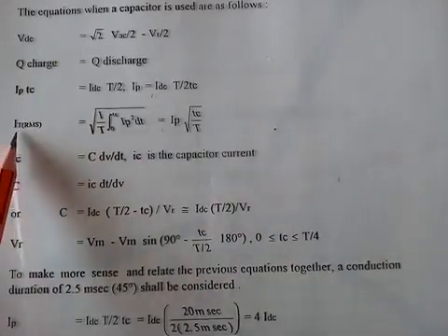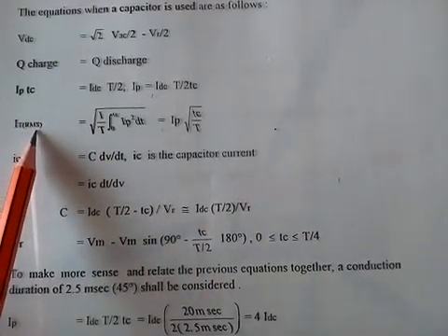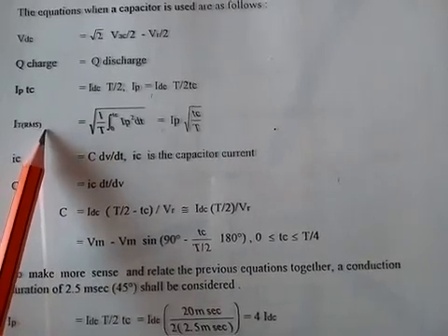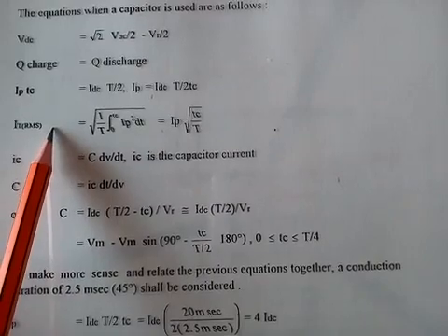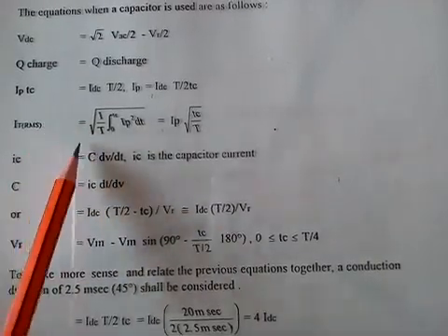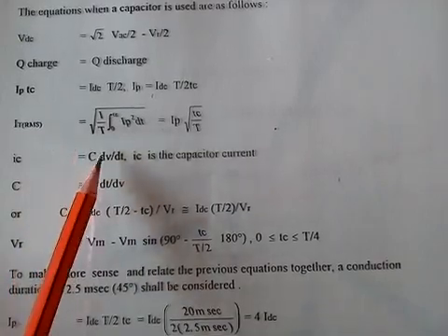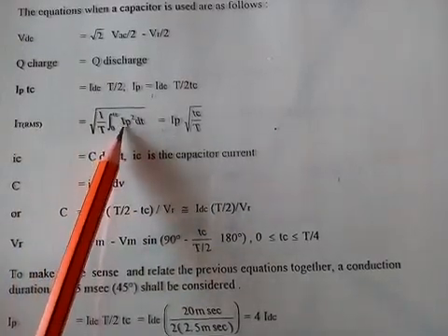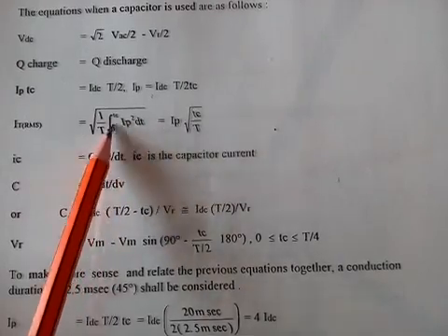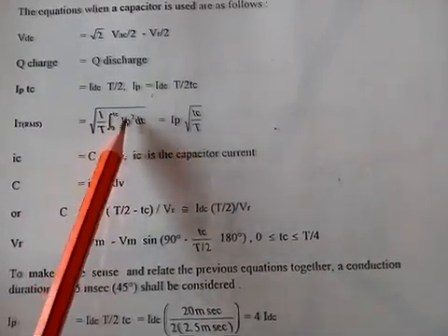And the RMS in this case in the transformer, when we made our assumption that it's like that pulse that we've seen earlier, the RMS for such a waveform will always equal the integral of I peak squared multiplied by dt. So you are finding the area underneath that one.